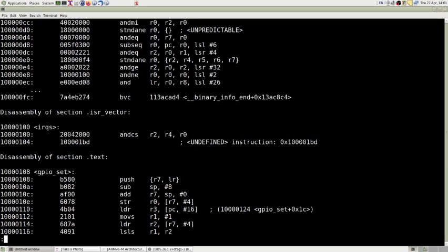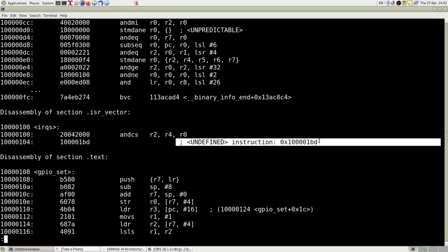And if we look here, top of the stack is the first value, and this is the address of main. Now again, we ignore this decompilation, it doesn't mean anything, and it says invalid instruction. Well, yeah, because it doesn't decompile to valid thumb code.